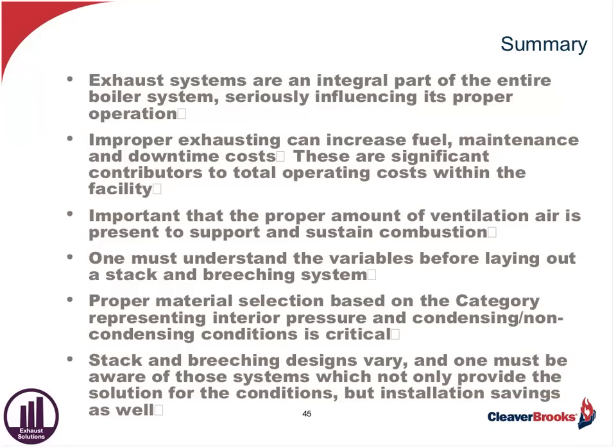And normally, if you're talking temperatures outside of 10, 15 degrees, 20 degrees, something like that, it doesn't really cause a problem. When you get into some real cold temperatures, say northern Canada, or even here in the States in the lower 48 or 50, you're going to get into situations where it's really, really cold. In that case, you're going to probably have to think about air heaters or electric resistance, something to heat that air before it comes in.